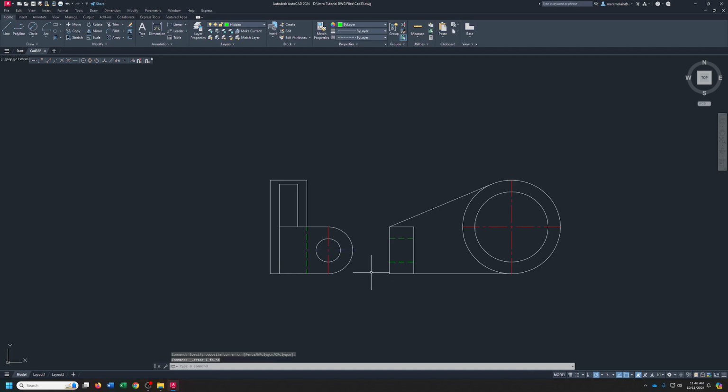And I'm just going to delete that one, come back, rotate, don't forget to right click and hit copy, and there we go. So that's got that one. All we need now is a couple of hidden lines. So we will line, I'm going to line it with this one. Start there, come across to there, and I'm going to offset the diameter, which in this case is 3. Go straight down. All right, so there's those hidden lines and everything is in place.